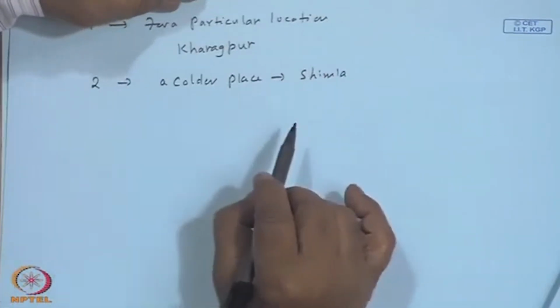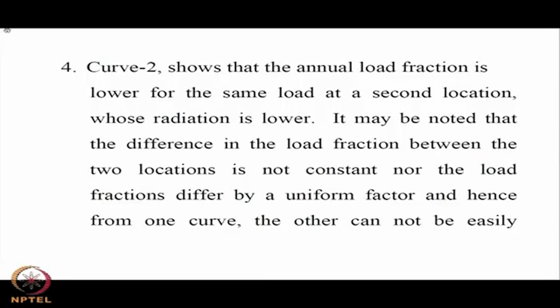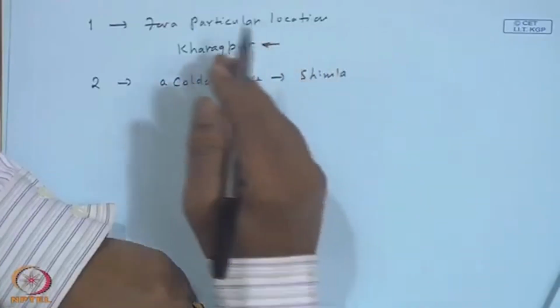Useful energy delivered by the collector is lower and the load also is higher, if it is a space heating system. Or even if it is a water heating system, simply, your T ambient or T minimum inlet temperature to the collector will be much lower than what it could be in Kharagpur or Chennai.